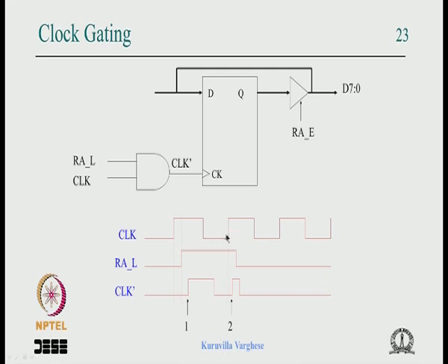at this edge. It is too early. We have a clock edge here, but maybe that is too early, because we decide the clock period depending on the TCQ, TCOMB and T setup, and we accommodate that in a clock period. But here the timing available from the clock edge to this clock is only little. So it's too early for registering. Maybe this is right, like we have decided that the data appears here, but then you know that